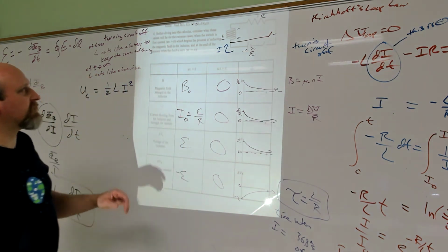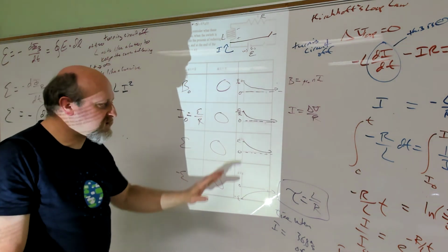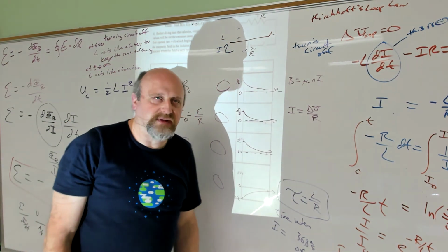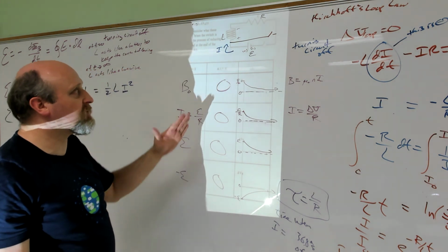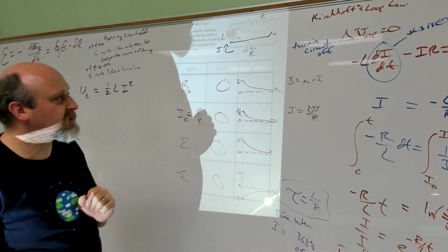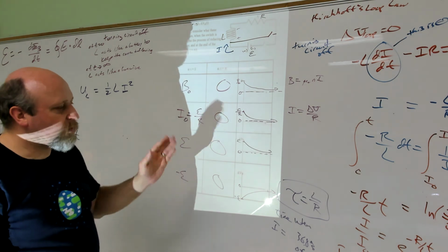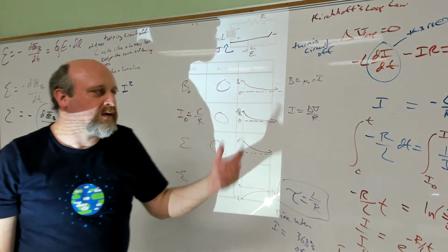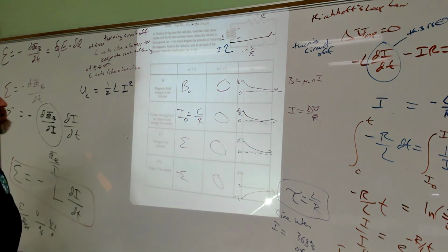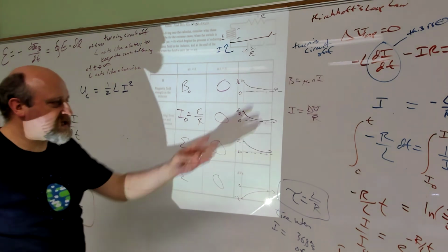If I was turning the circuit on, if we did that derivation, you'd get that same time constant. That'll be the time to get to 63.2% of the maximum current in the circuit, because that'll be 1 minus e to the negative 1 when you're at one time constant. Okay, that's it. Hey, like I said, this was the easy derivation.